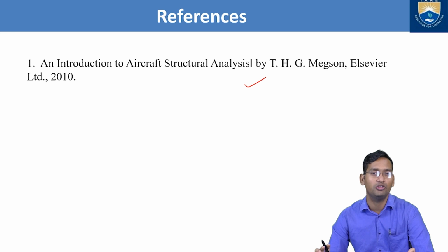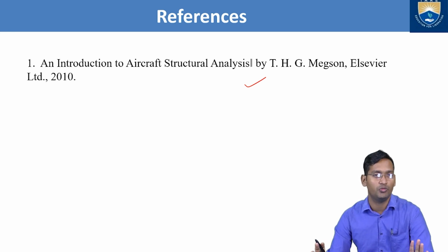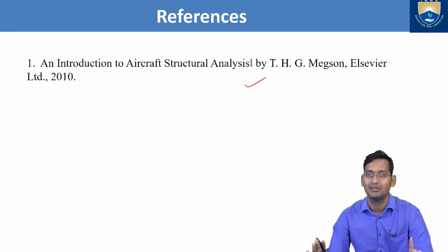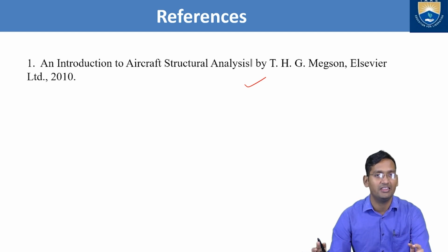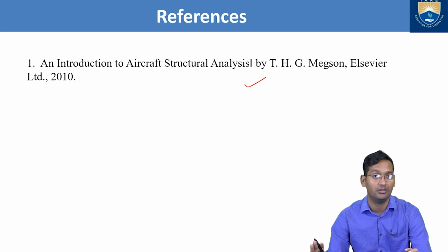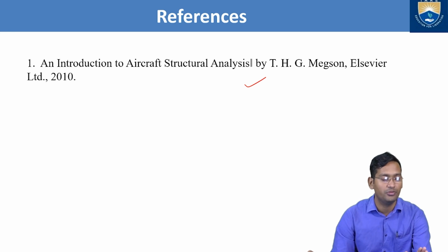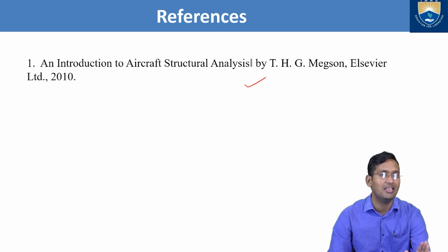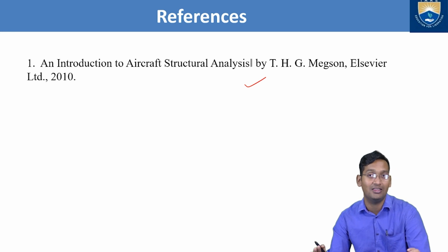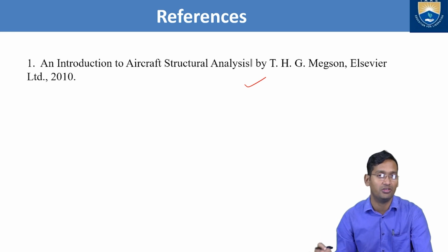Here only one thing you have to remember: first, the 4 equations you just found by the shear stress distribution formula, that main formula. After finding that, take the moment about one particular point that you have taken as reference. Next, consider vertical equilibrium and horizontal equilibrium, right? So after considering these 3, you will have 3 equations in terms of shear stress. Now, the first 4 equations you have, replace those values of the shear force in the next 3 equations, that is, equations 5th, 6th, 7th.